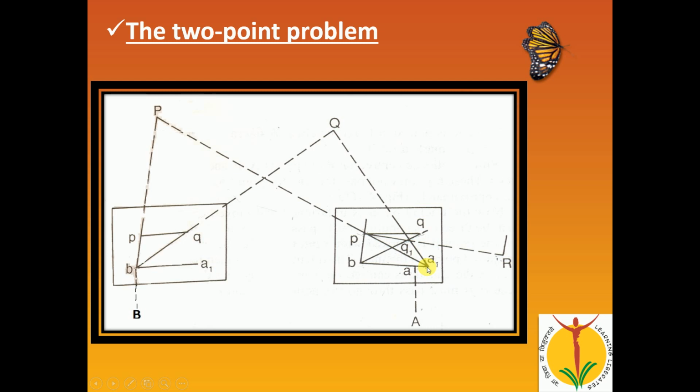After transferring the station exactly, setting the table over station A, we have to do the orientation, and then we have to do one thing: alidade touching point A and bisecting point P on the drawing sheet, we are going to bisect the ranging rod at P. Suppose this line exactly passes point b, and in a similar way, alidade touching at point b and bisecting the ranging rod at Q, that line should pass through point Q.